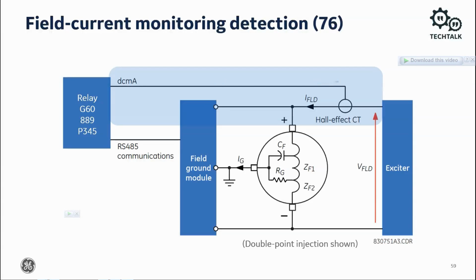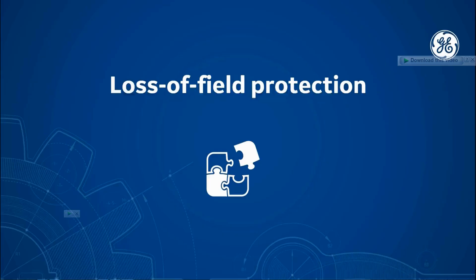The maximum and minimum settings configured for scaling of this DCmA or CLIO input are used to get the per unit values of field current. When a generator loses field excitation, it ceases to operate to provide power.